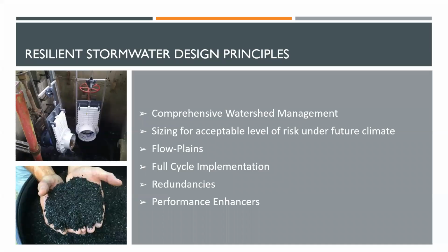But it basically means making sure that we're working across all of the relevant agencies, not just thinking about stormwater management in a silo, but how does it affect our floodplain management, or our dam safety agencies and transportation agencies. Meanwhile, what are the impacts on stream restoration or our stream corridors? How are we implementing stream restoration in combination with upland practices so that future intense storms don't blow out something that we've invested a lot of money in?